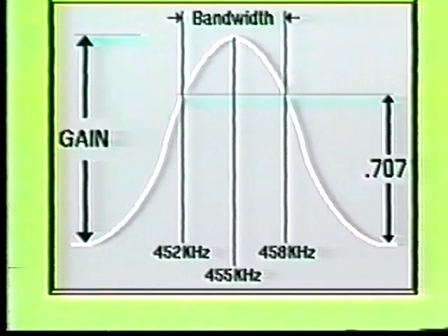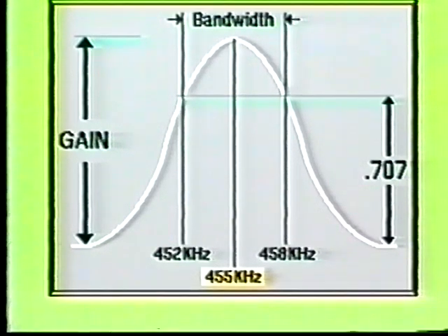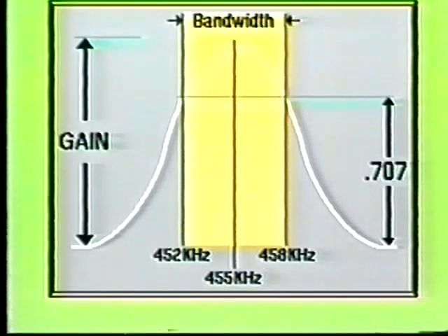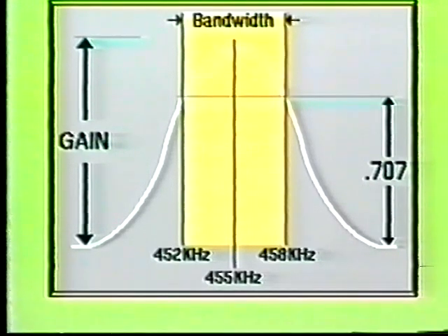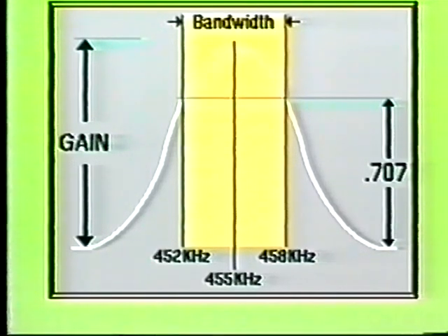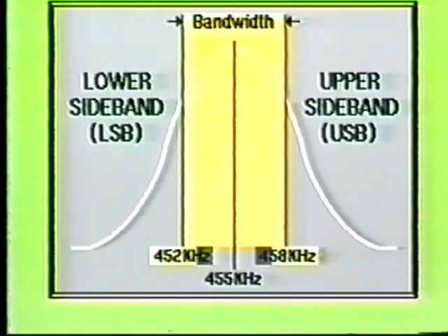The intermediate frequency amplifier stages are factory tuned to 455 kilohertz. This allows the stages to produce optimum gain with a sufficiently narrow bandwidth. The narrow bandwidth improves the sensitivity and selectivity of the incoming signal, but in the same respect, it also produces a poorer signal for the audio frequency amplifier stages due to the fact the sideband frequencies are squeezed out.